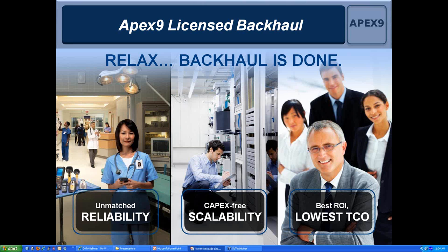For people who have a need for fiber up the tower, the issue is that it obviously increases the cost because now you're running fiber instead of coax and it becomes a little more messy. But there are the benefits of lightning protection on that side. Well, not always though, because you still have to run power up the tower. So, ground potential. Yeah, well, why don't you shoot me an email offline, for the person who asked that question.